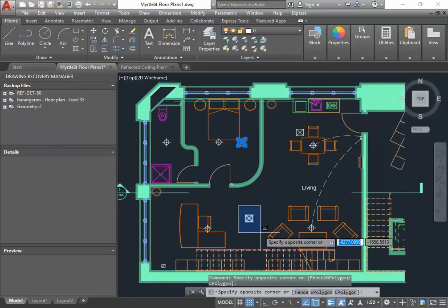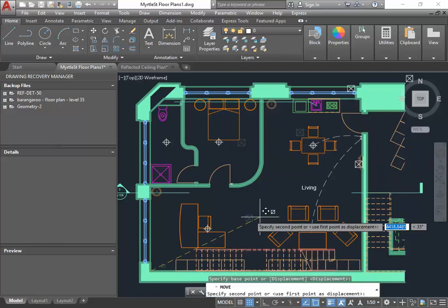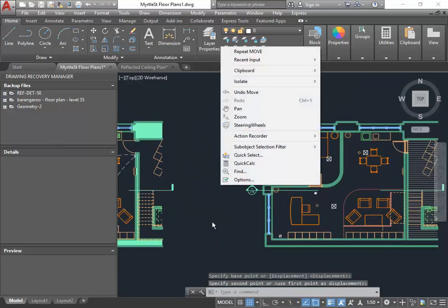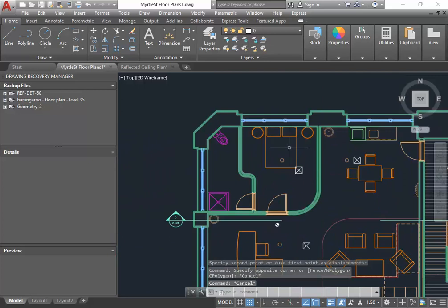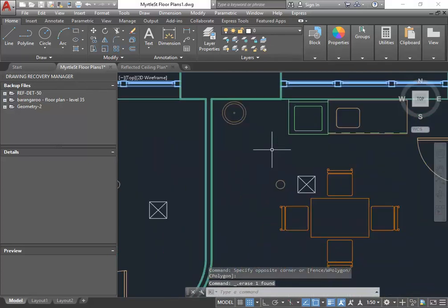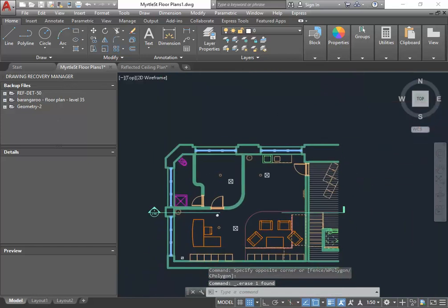And then you can move it over to your ceiling plan afterwards. Beauty of using AutoCAD, it's easy to locate things precisely using a base point. And what you should remember is that your ceiling plans shouldn't show all of these furnishings that are on the floor. So I'll sort of clear those out as I go.